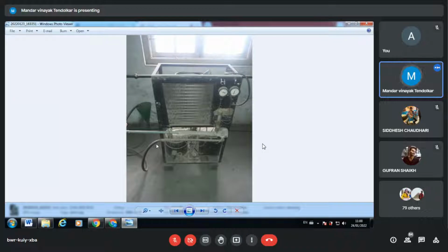Circuit is the same. There is a compressor as it is shown over there, and in their video the condenser was right beside it. In our case, it is mounted above. Nothing other way different. Then they were using, I think, a solenoid control expansion valve. Ours is the old one, copper capillary. And then very similar to their box in which that water was stored.